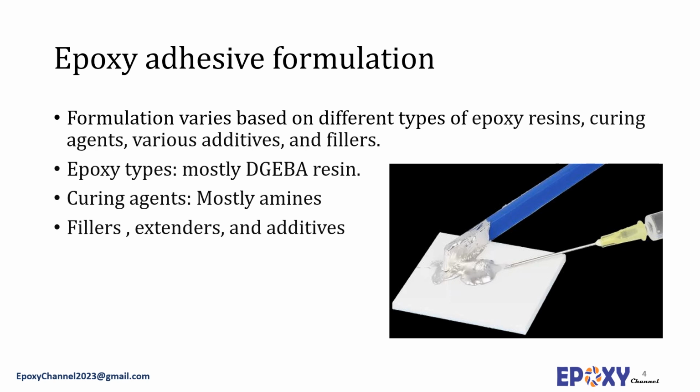However, the most common epoxy systems employed in epoxy adhesives are diglycidyl ether bisphenol A resins. Low molecular weight diglycidyl ether bisphenol A is often employed in liquid and paste adhesive grades, whereas for conditions where structural integrity is required, for example, in film adhesives, higher molecular weight variations of diglycidyl ether bisphenol A resins are often employed. The next important factor in the formulation of epoxy resins is the choice of the curing agents.